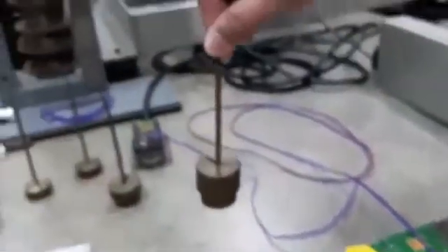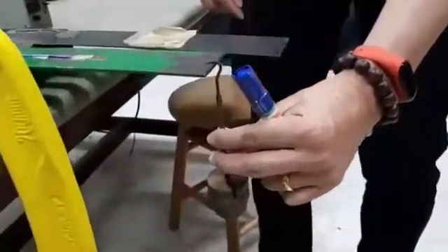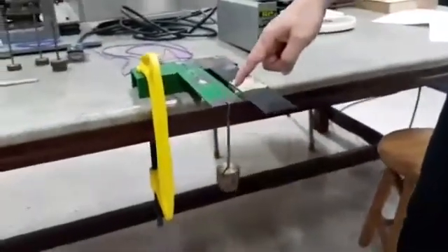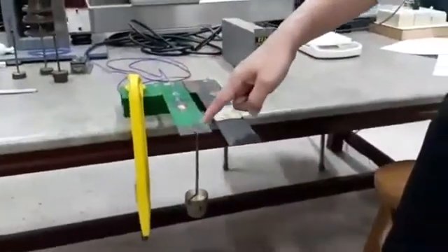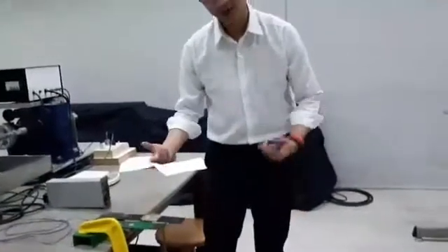And this is a mass. I'm going to hang the mass here, like this. Because when I hang the mass here, from the whole system, I create a moment on the cantilever beam. When I create a moment on the cantilever beam, I have the normal stress here. If I have the normal stress, I could find the normal strain. That's what I previously explained.